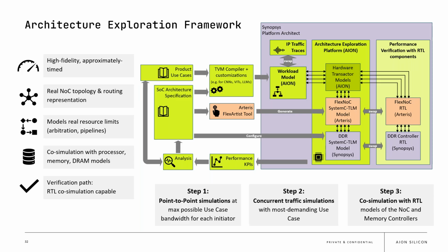And that is your architecture exploration platform. We typically build this in Synopsys Platform Architect, a well-known architecture modeling EDA tool from Synopsys. So that's the structure of how the exploration platform is constructed. And then you've got the workload model, which is the output of the TVM compiler. These are your candidate schedules, which are imported into Platform Architect. And then you run your simulations.